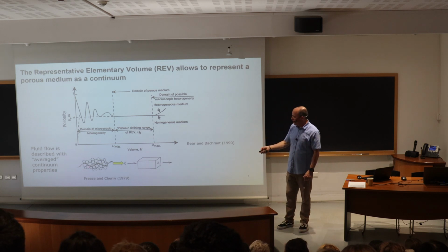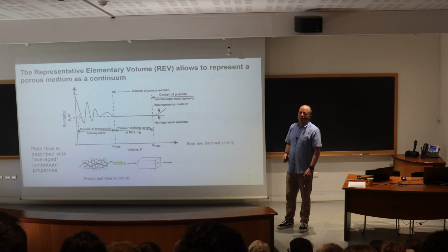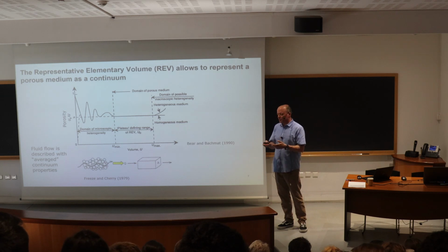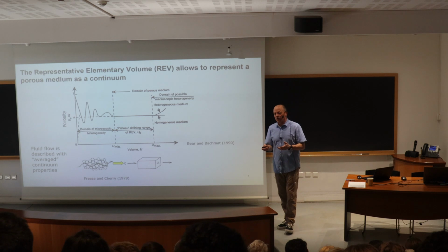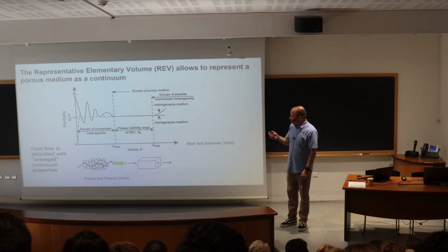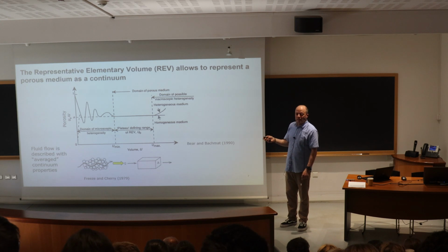At the pore scale, we might be able to represent all these individual flow paths, but we replace that by an equivalent specific discharge or Darcy flux, which is what we use. It could be an equivalent groundwater flow velocity, which is then used for transport representations. And we then leave the pore scale.